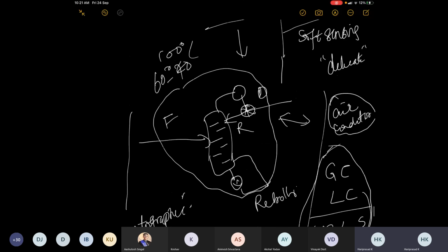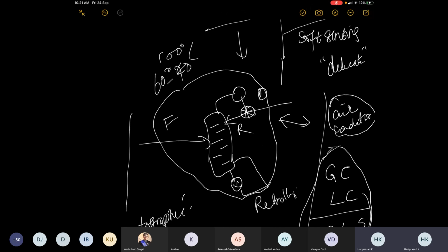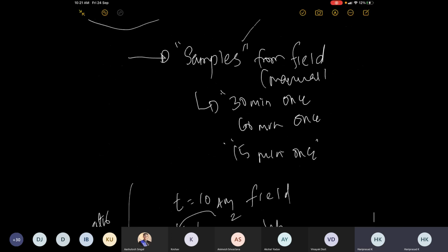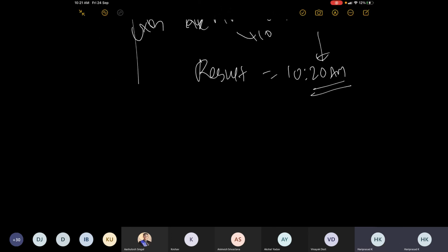So let's say the distillate is giving poor results. He or she would have to do some fine tuning, which essentially means playing with the reflux ratio, and probably firing up the reboiler a little more for more vaporization, or even cutting down the feed. Some decision may need to be taken in this middle. What to do? Because you don't have the information with you.